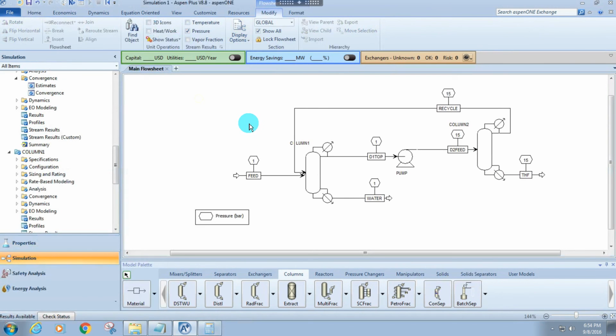Never input a stream of 1 atmosphere into a 5 atmosphere block. You know what I'm saying? Where did that pressure, that compression come from, right? Aspen will do that calculation because once it goes in as 1 ATM and at the block it reaches 5 ATM, it will overwrite that pressure that was coming in, right? So it magically will have 5 ATM. But in real life, that's not the case, right? So this is just to reflect a more realistic operation. Aspen will run it without this pump.